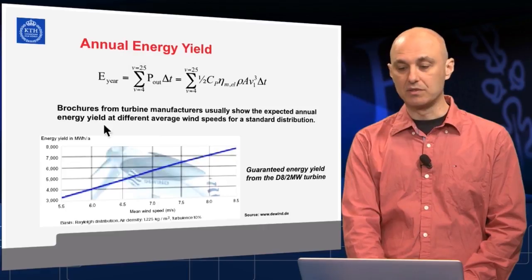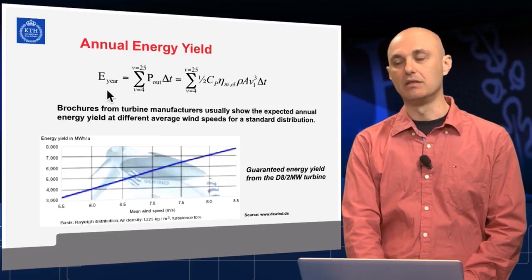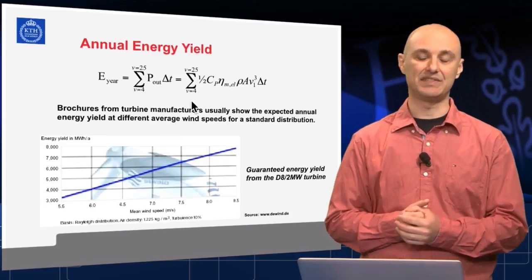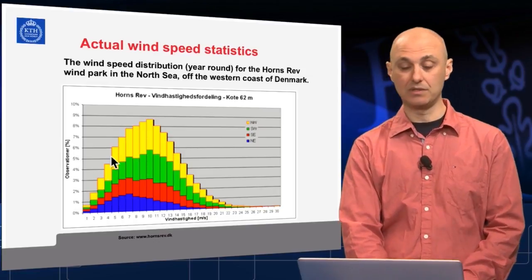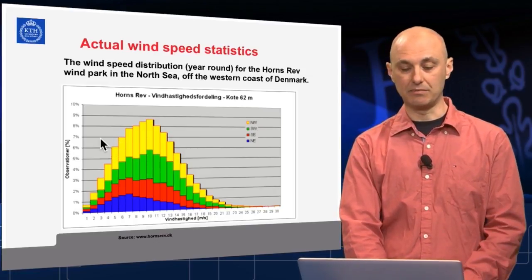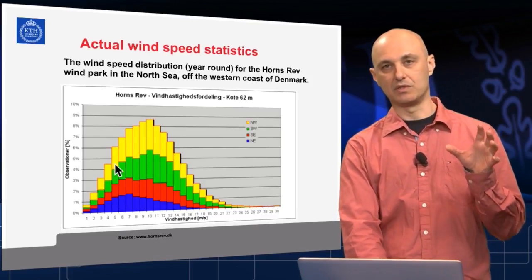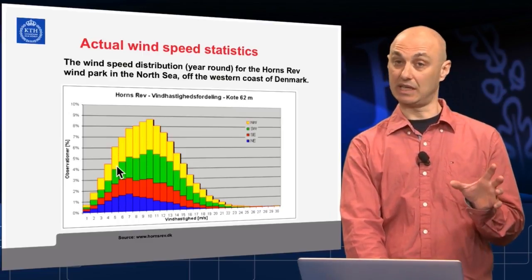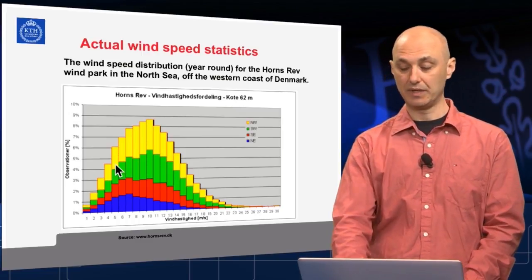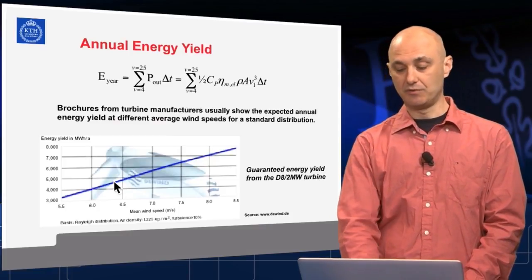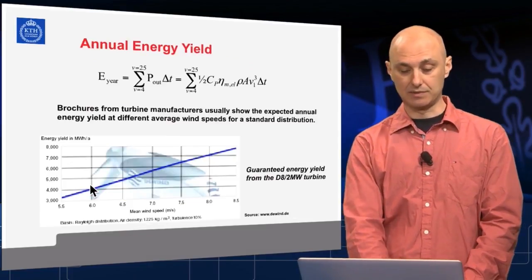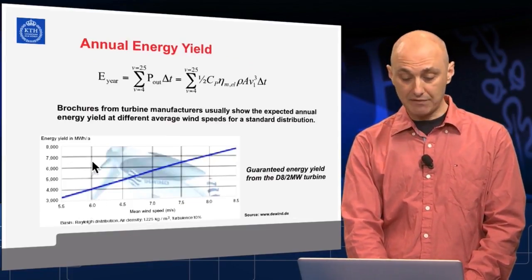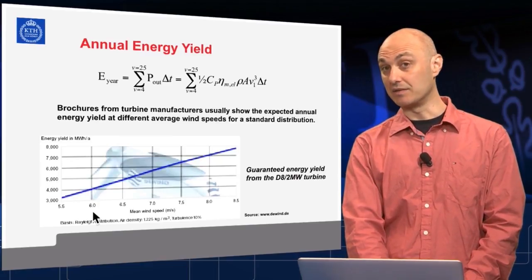The annual power output from a given wind turbine can be calculated in this way: how long, as a percentage of hours within a certain span of time, say 1 year, a wind speed occurs, and how productive your turbine is at that wind speed, typically under standard conditions, and summing them up for this particular standardized wind speed distribution, you can summarize this for an average wind speed of, say, 6 meters per second.